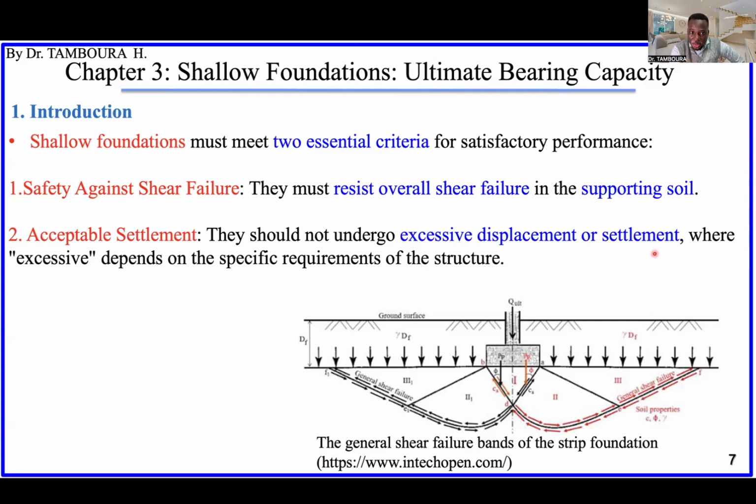It will depend on the specific requirements of the structure. Each project has specific requirements depending on the importance of the building. If you are building, for example, a hospital, the requirement will not be the same as when you are building a residential building or a primary school. Each project has some requirement that we have to meet. The settlement of the foundation should not exceed these requirements.